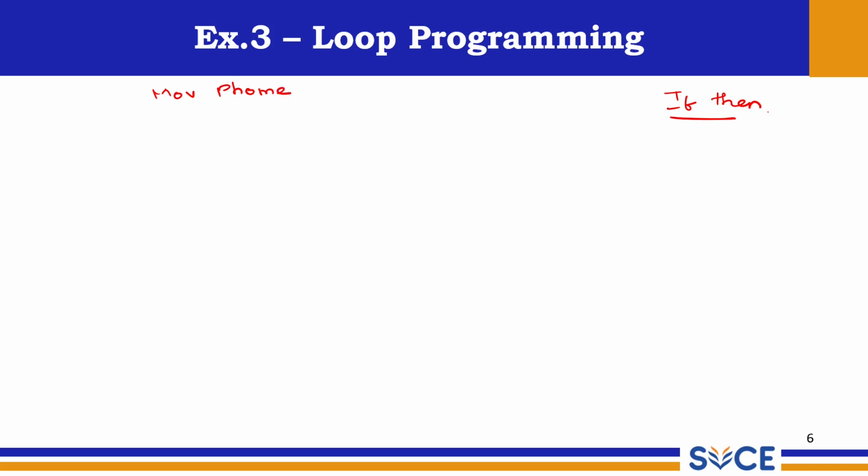Whenever we do this, we should have a counter, right? Because our requirement is 5 times. So counter, let me give it as M0. Again, this is zero, not the letter O. If you give the letter O, it will be a syntax error. So M0 is equal to 0. I am putting an apostrophe and giving this explanation: it is the default zero, not the alphabet O. This is the portion where the majority of students make mistakes when they type. So it is M0.